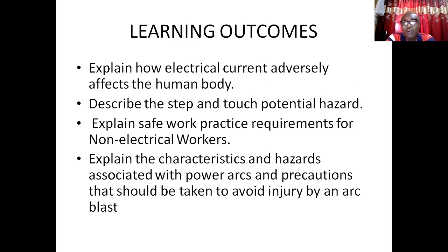Explain how electrical current adversely affects the human body. Describe the step and touch potential hazard. Explain safe work practice requirements for non-electrical workers. Explain the characteristics and hazard associated with power arcs and precautions that should be taken to avoid injury in case there is a blast.